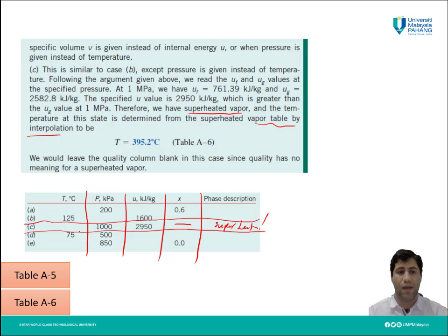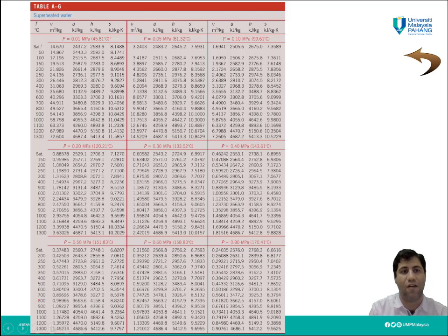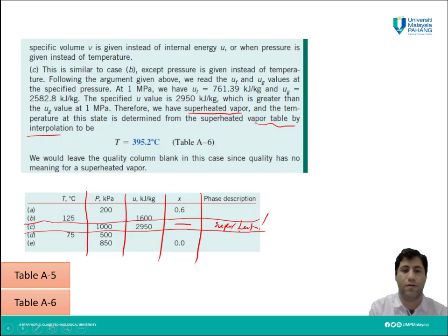state as well. And we need to find temperature for this pressure. Again, we need to go to table A6. We have pressure also in this table. Then we need to find temperature for this pressure, which I'm not going to do that because this value is not directly in the table, and we need to do interpolation to find this temperature.